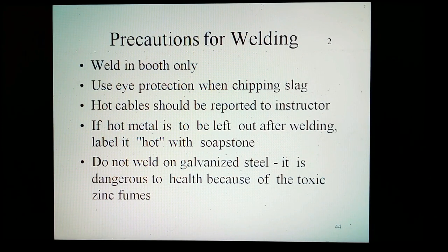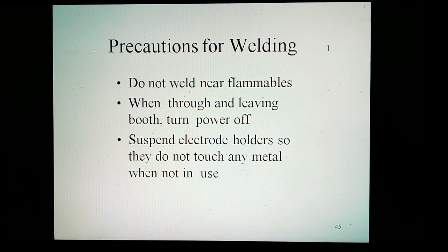If hot metal is to be left out after welding, label it as hot with soapstone. Do not weld on galvanized steel as it is dangerous to health because of the toxic zinc fumes. Do not weld near flammables. When through and leaving the booth, turn power off. Suspend electric holders so they do not touch any metal when not in use.